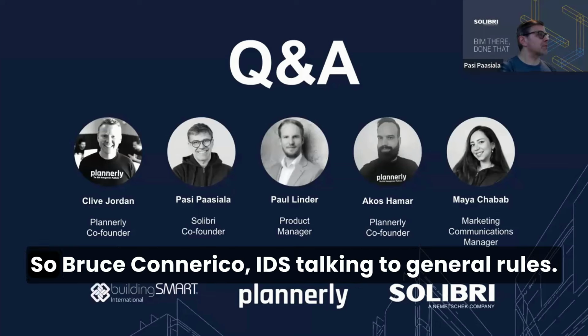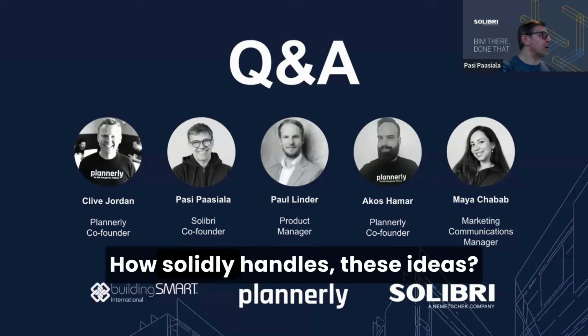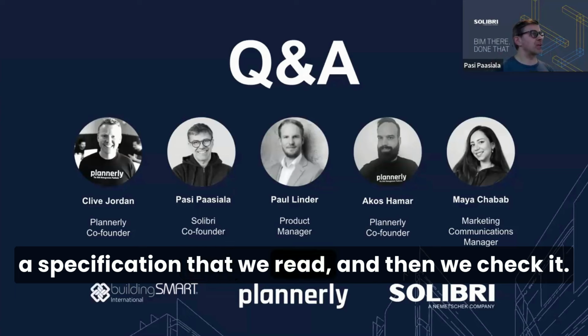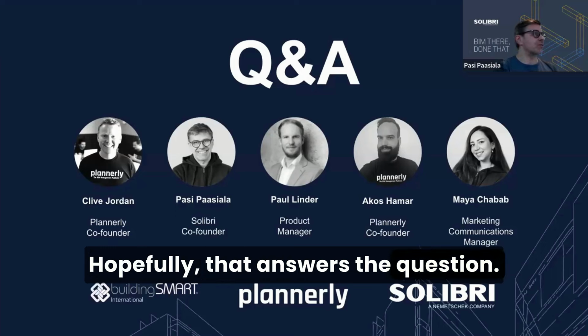All right. So Bruce Carnerico, he's talking about general rules. Maybe there is some misunderstanding about how Solibri handles this IDS. For Solibri, this IDS is kind of a parameter, like a specification that we read, and then we check it. So we check the IDS specification, and that defines the rule, what should be checked. Hopefully that answers the question.